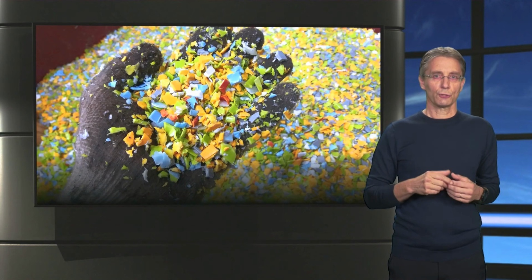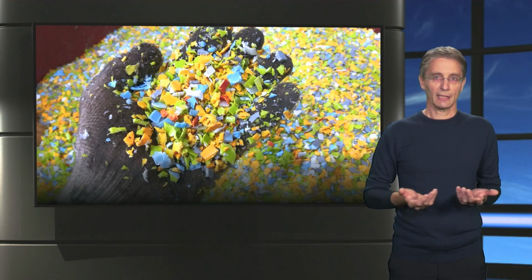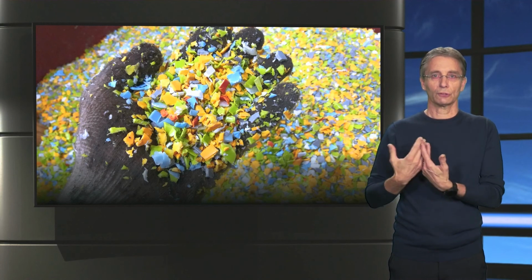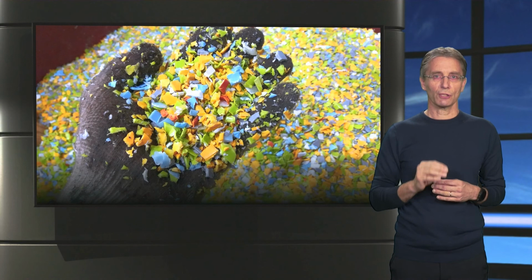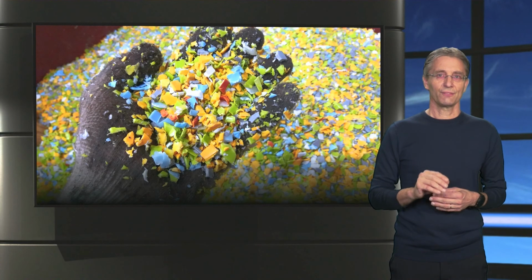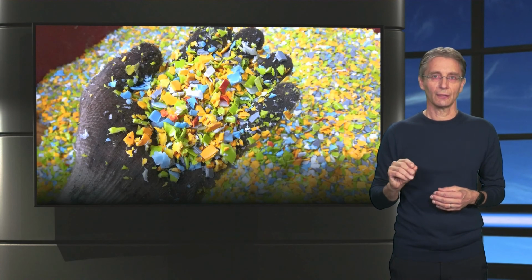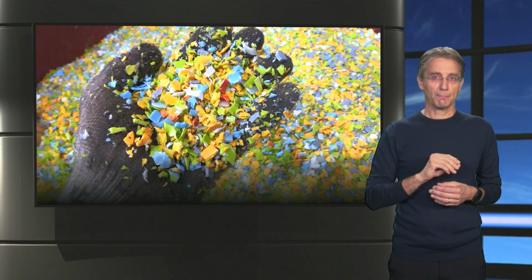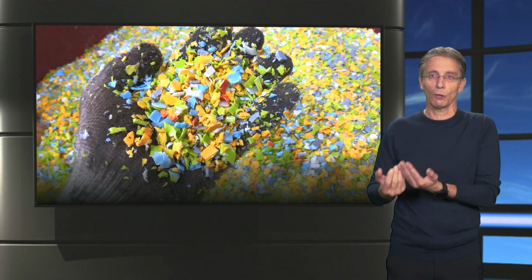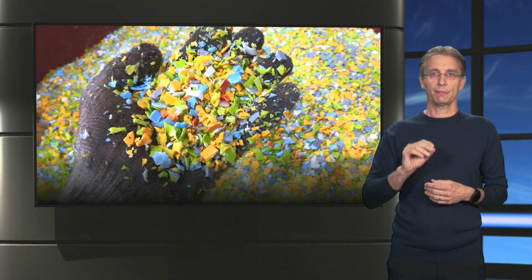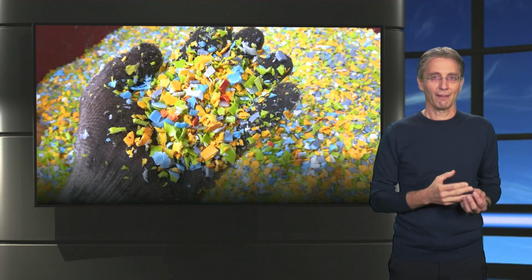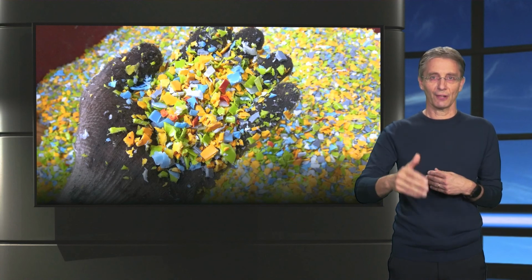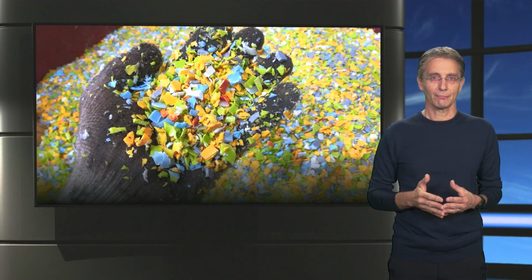After sorting, certain flakes will remain undetermined, either because they are too contaminated or because they were not successfully identified. This residual stream will most likely be incinerated for energy recovery. In a circular economy, this is considered a leak in the system. However, in some cases, mixed plastics can be applied in products of relatively low quality. But this is to be avoided too, as it implies that the product is made with ill-defined composition. This makes its future processing after the next life cycle very hard.